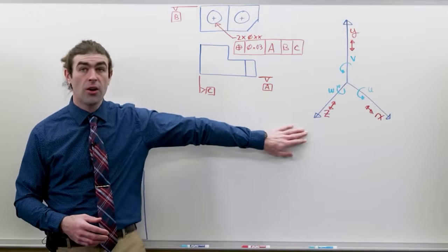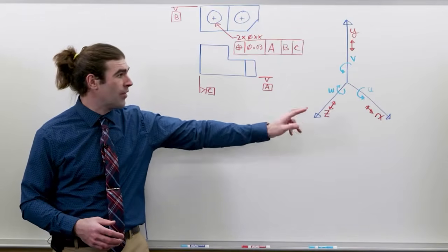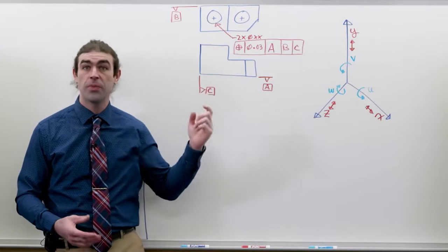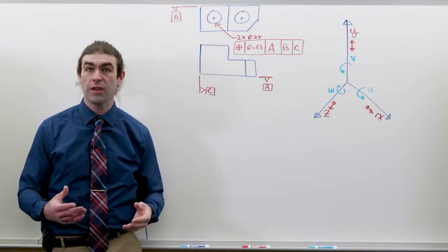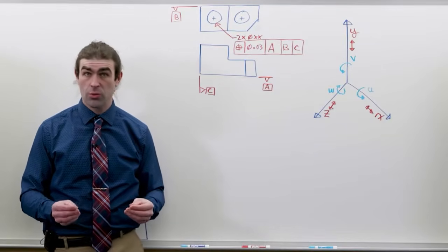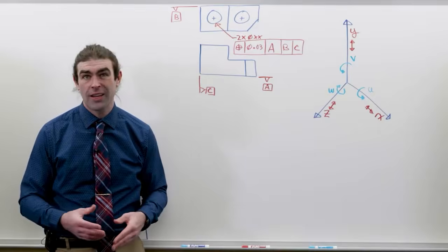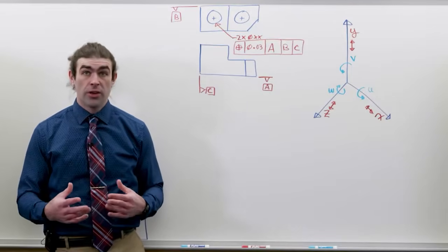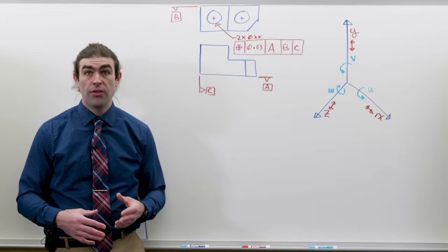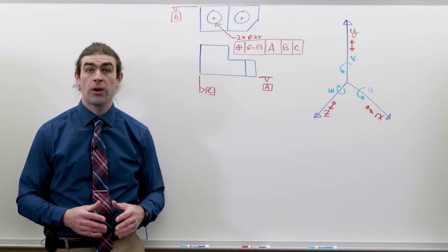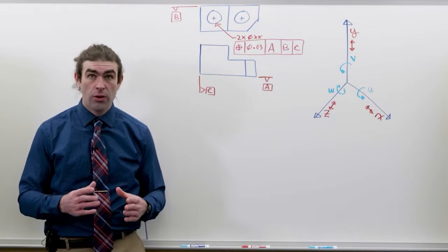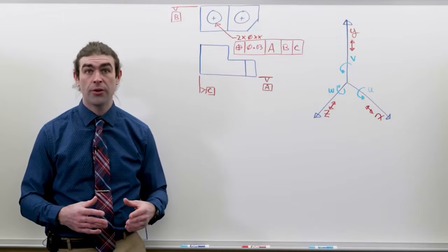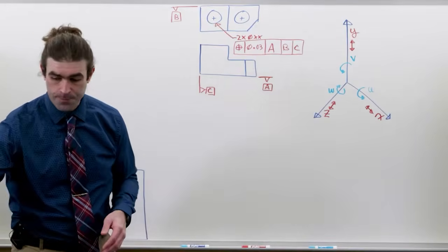Now, our datum reference frame looks like so. We have one direction in X, another direction in Y, another direction in Z. This is our 3 dimensions, and it's what we usually need to measure parts. If parts are really, really thin, like sheet metal, sometimes you only need to worry about 2 dimensions, the X and the Y. Now, there's another concept called degrees of freedom. This is really important for inspection. It is the order in which you constrain the feature so that the feature doesn't move around on you while you're inspecting. Let me show you how it works.